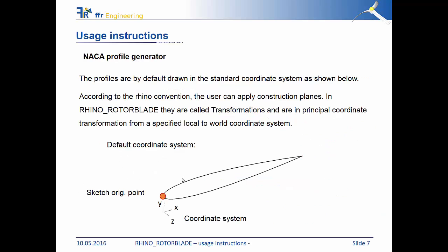One important thing is that we work here in the Rhinoceros CAD system, of course, as you will see in a second. In it you consistently work with coordinate transformations and construction planes. Some people who are more familiar with products like NX or Inventor might be more used to the sketch-based approach to drawing. Here in Rhino it's different, you have a real freeform system. Nevertheless you have construction planes, so everything is designed on the construction plane unless you define it differently. And the same holds here.